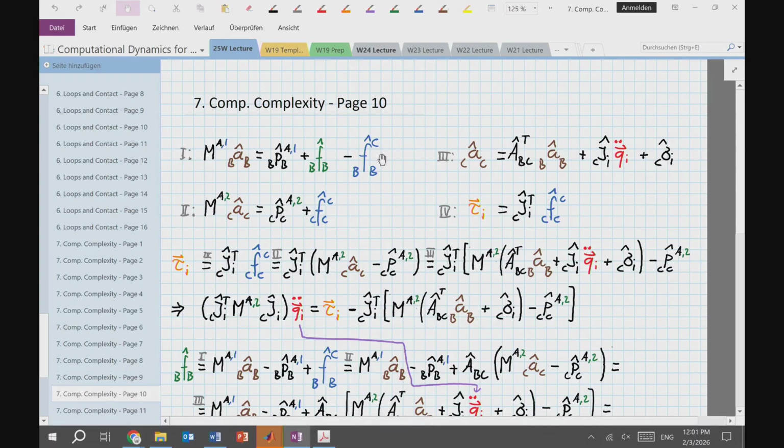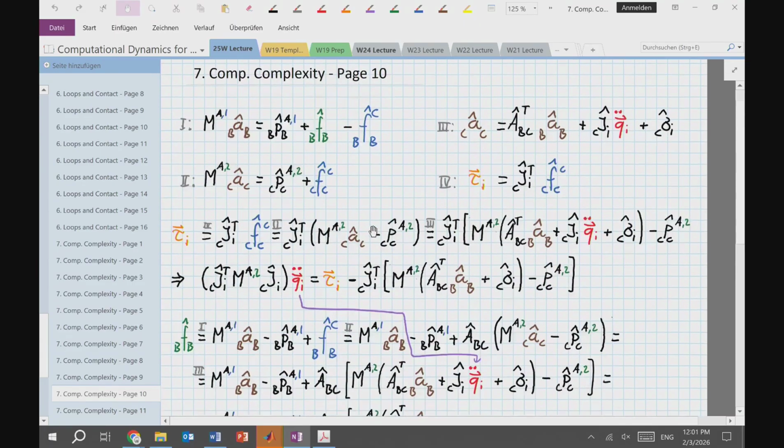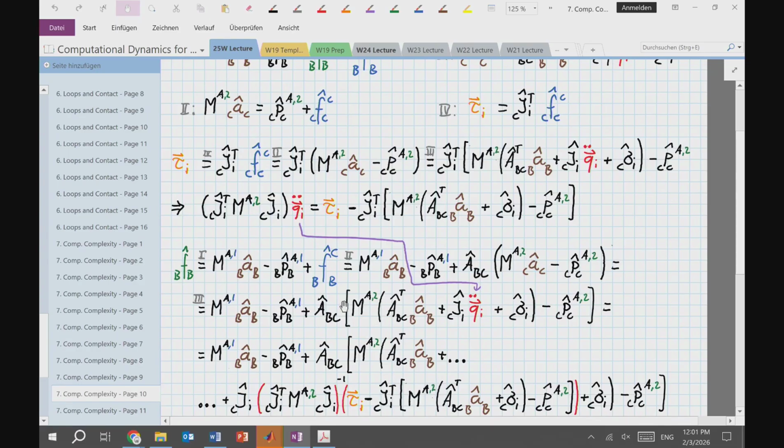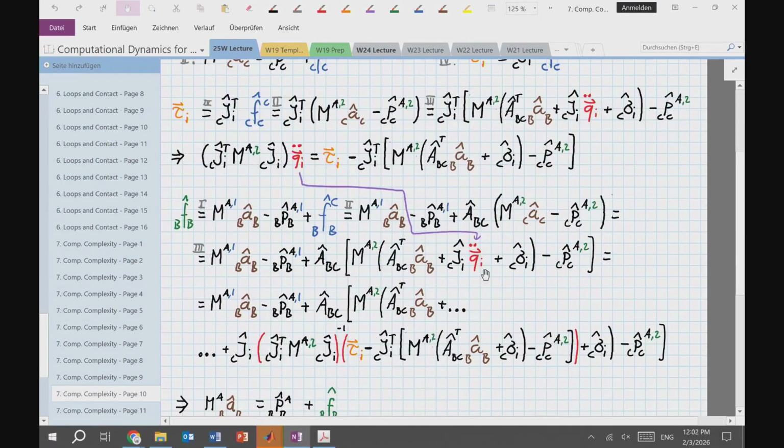And you see there's a bit of a coordinate transformation happening with this ABC hat, because this is stuff expressed for the center of gravity of body B. This is stuff expressed for the center of gravity of body C in the respective coordinate systems. So there is this transformation matrix. But other than that, I just plug this in. Then I have ACC as my unknown. I take this entire expression, which I get from my motion across the joint. And then I have Q double dot as my unknown. And that Q double dot I can then insert here. And I can compute FBB.